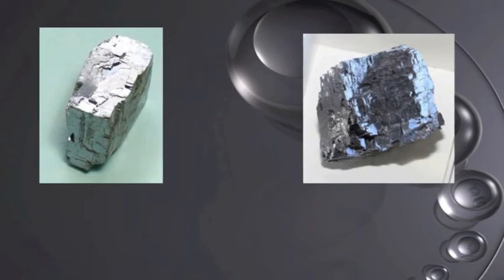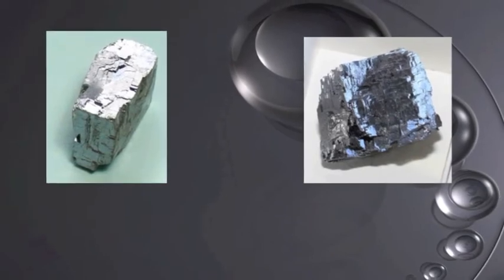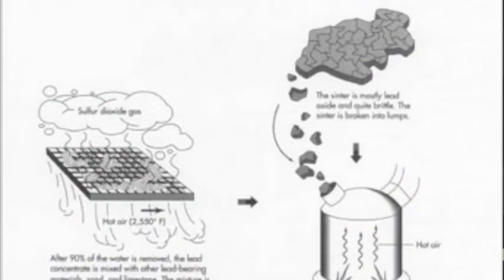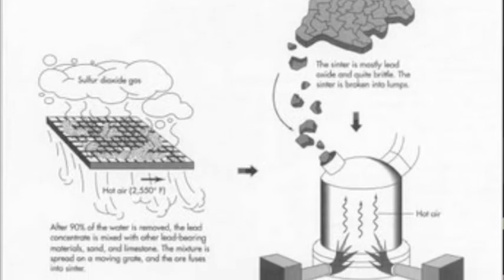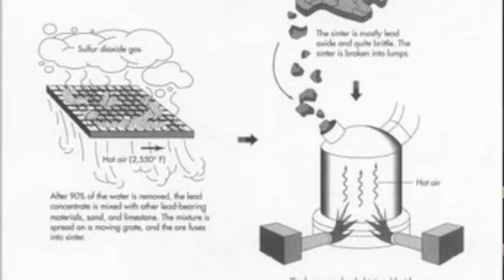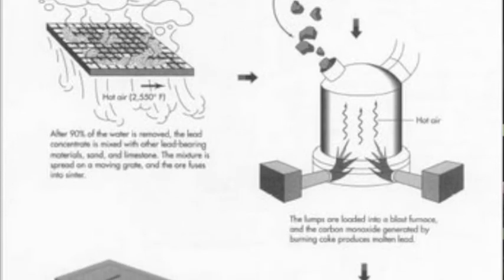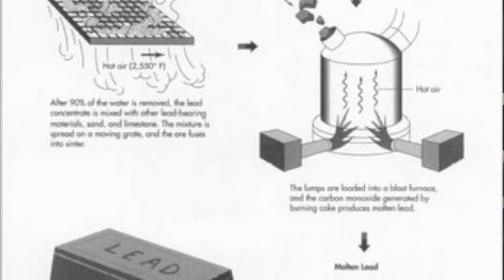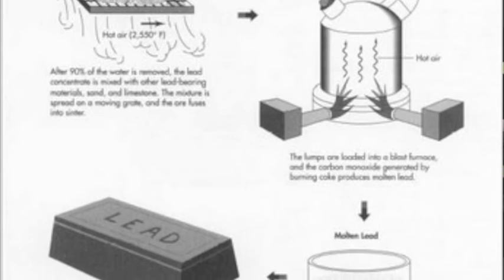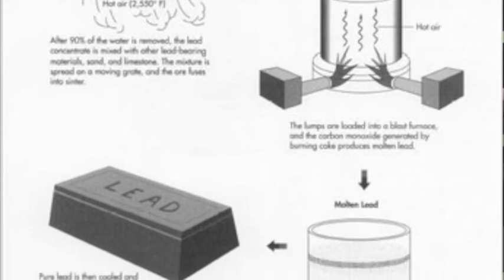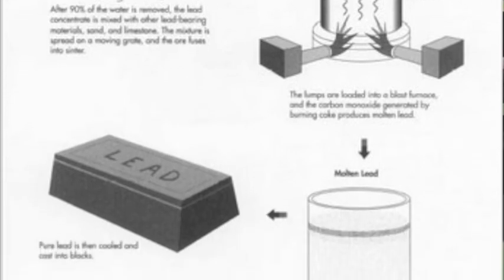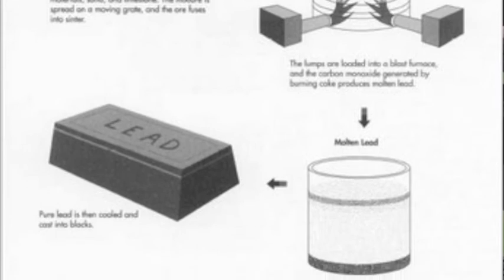Lead is a chemical element that exists in nature as galena and lead sulfide in mines under the ground. The lead has a simple process to make. After mining, it is floated to separate the waste from it in tanks by adding water and oil. After that, it is heated in a furnace to 800 Celsius degrees. Then it moves to another furnace to get rid of monoxide, to get the pure molten lead,